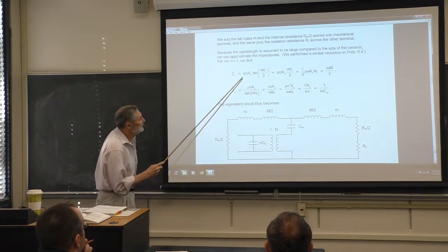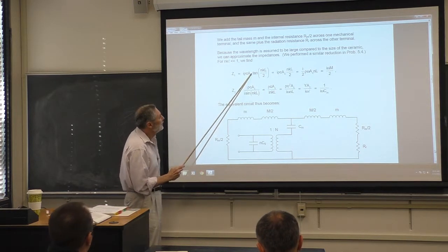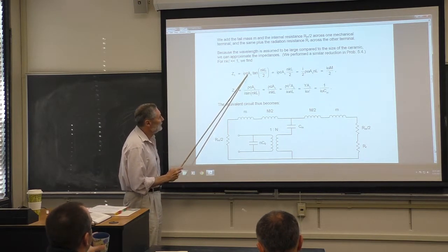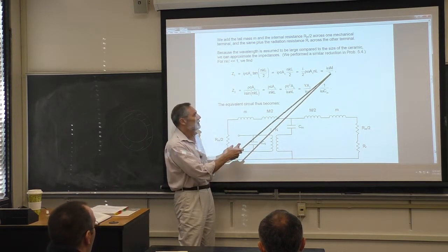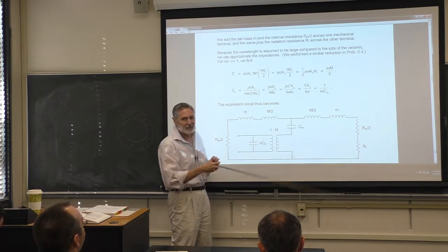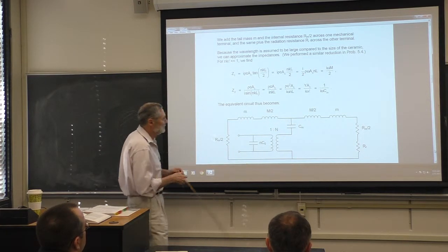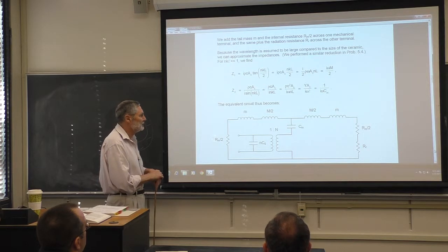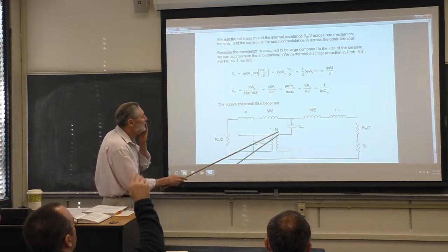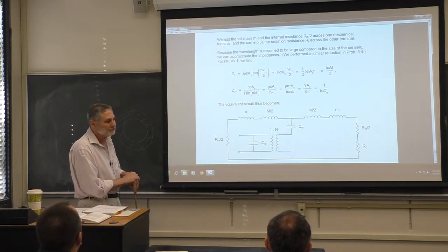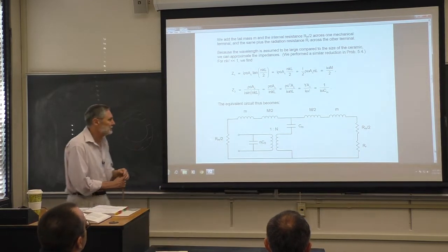In the long wavelength limit, this is a general standing wave expression, which Brian really likes to put down. But this simplifies greatly when it's uniformly stretched and compressed. It's just half the mass. It's an inductance, I omega times an inductance, where the inductance is half the mass. And this becomes a pure stiffness. It's 1 over I omega C, like a capacitance, where C is the mechanical compliance. The little n in there is the number of stacks, right? Yeah, we have to keep big N like we defined it long ago, as the turns ratio.